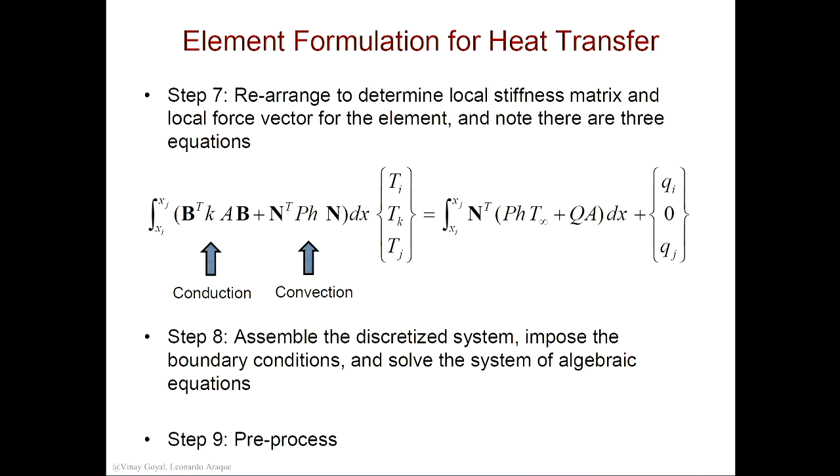And this equation is only for one element? This equation is true for one element. I derived it for one element. Even in one element, we cannot have different conductivity. So if you have multiple elements now, and let's say the first 3/4 of the material is steel and the remaining material is aluminum, then I'll put elements here, and I'll stop right there where the aluminum and steel boundary is, and I'll put a new element that represents the aluminum.